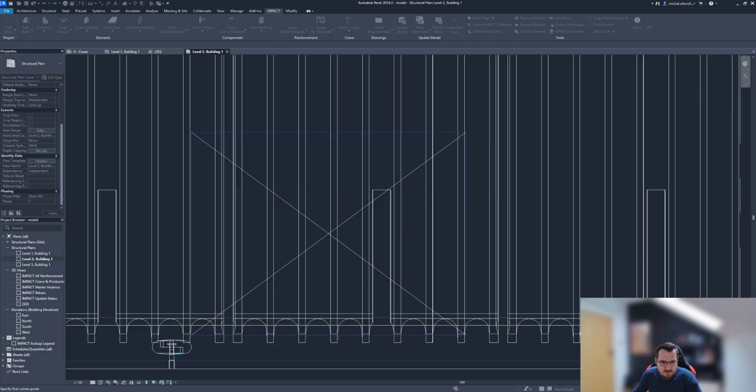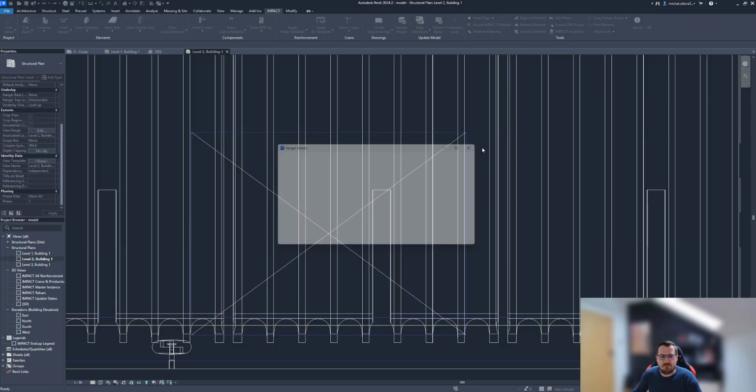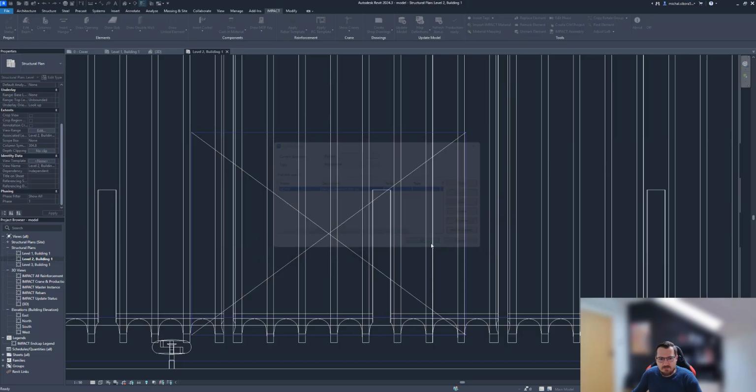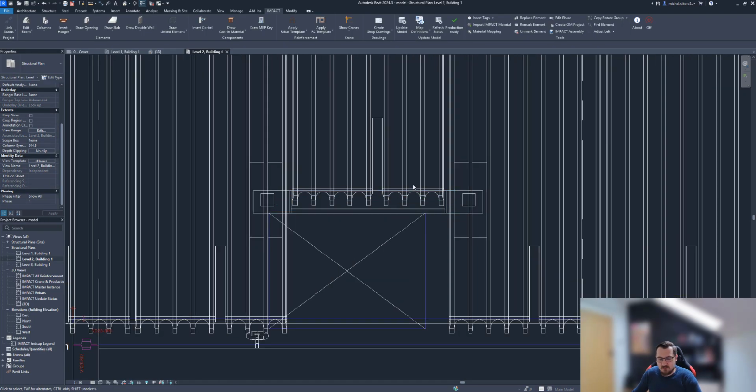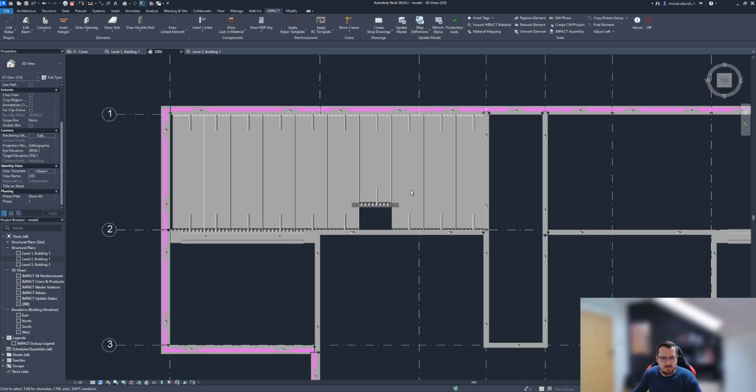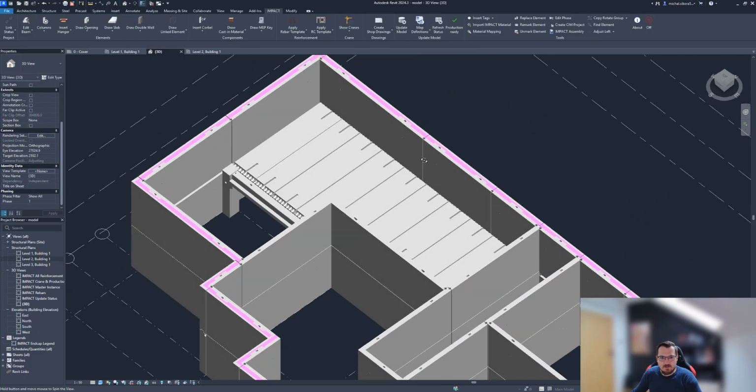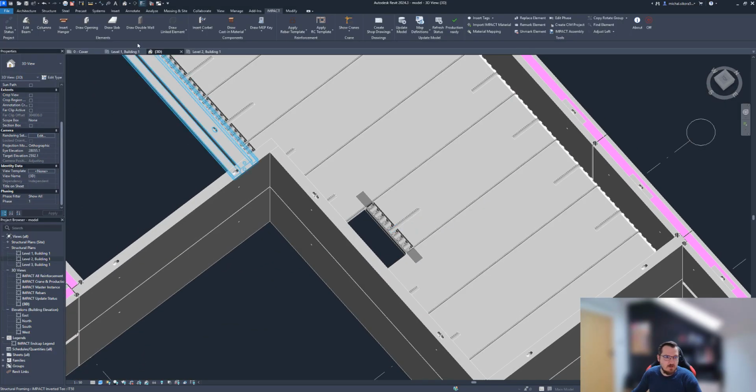I want to get a cutout from this hollow core, yes, to somewhere here, like that, and I'll select this hanger. I've got a hanger defined, so this will allow me to edit this hollow core so it's hanging and supported on this particular edge, and of course it will be visible in the 3D view for us, like so. So we've got a hanger.